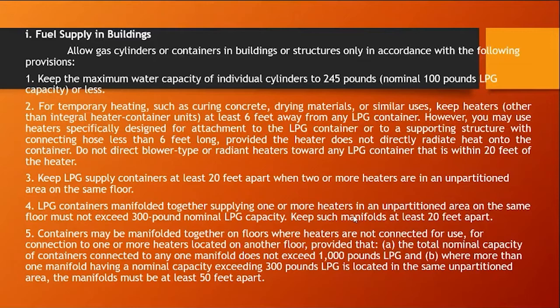Next is LPG containers manifolded together supplying one or more heaters in an unpartitioned area on the same floor. They must not exceed 300-pound nominal LPG capacity. Keep such manifolds at least 20 feet apart.